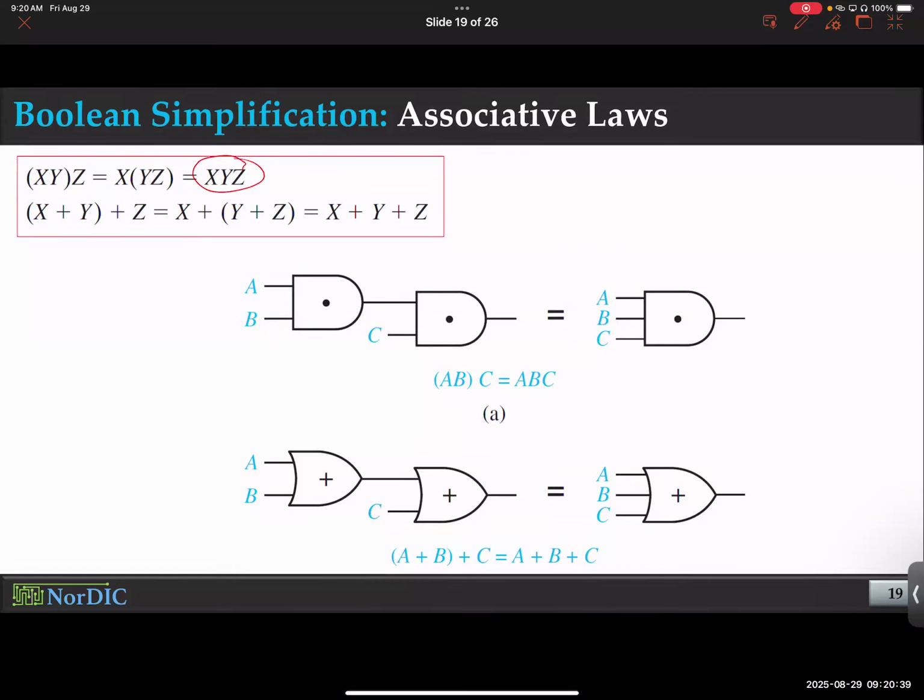You might have to use four inputs because it might simply become too area expensive. Anytime you break something into multiple components, it's going to take more time versus something that is integrated. So if you have a four input integrated gate, it's going to take less area, but it will be slower. You see that, folks? Okay, so these standard cell libraries have flavors of the same gate, two input, three input, you name it.